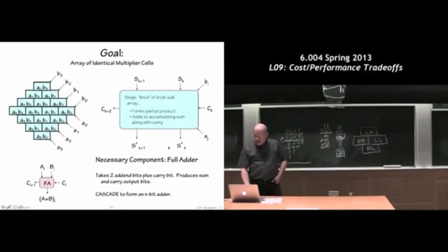So in general, what I'm going to do is multiply A times B to come up with a 2-bit result. I'm going to add it to those bits of the partial product coming down from the top, and with a carry in from any carry outs of previous operations in bits with less significance, arithmetic significance, and I'm going to produce a 2-bit sum and a carry out.